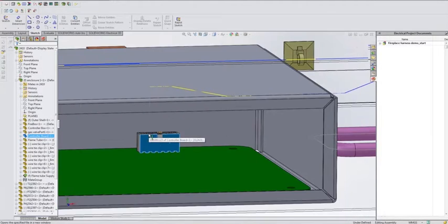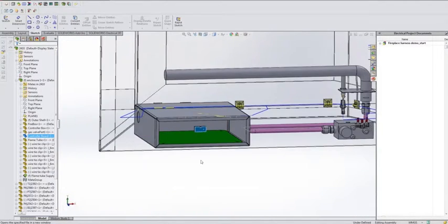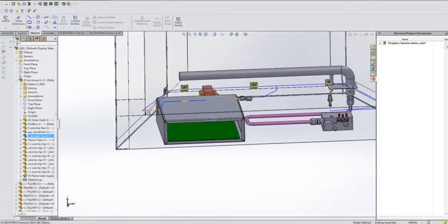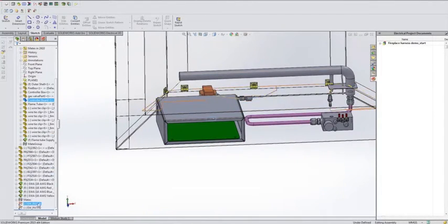Okay. Before I go through this, you'll see that I have these sketch lines. They're both yellow and blue, and that represents a sketch path. I've already done this. It's a 3D sketch, something inside of SOLIDWORKS, where I'm giving it a predefined path, a suggested route to go along. So when I route up this harness, and how that's going to be driven is off of 2D, it's going to follow along that path.